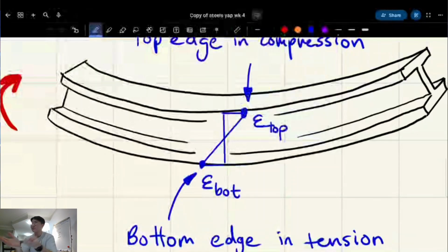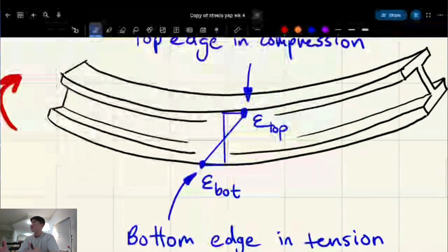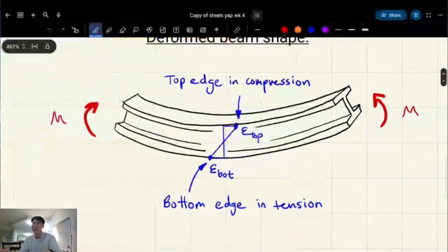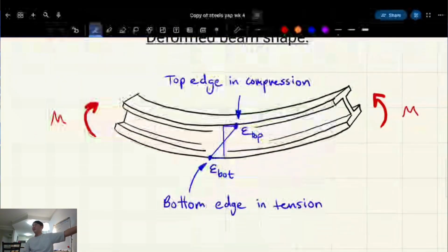And so there's actually 2 forms of strain. There's tension and compression, right? So if you're stretching something, pulling it apart, you're putting it into a tensile strain, and if you're pushing it together, you're putting it into compressive strain, right? So when I bend the beam like this, which is the shape it's gonna go into under gravity loading, is the top gonna be in tension or compression? And what about the bottom?